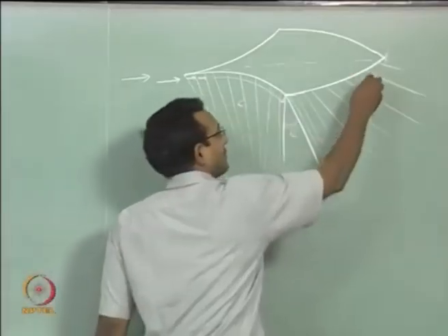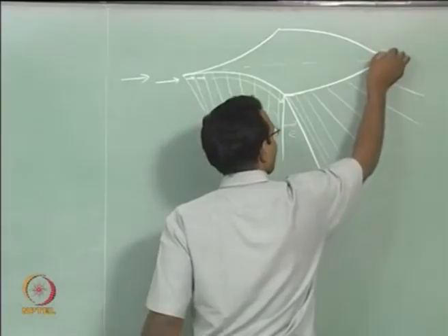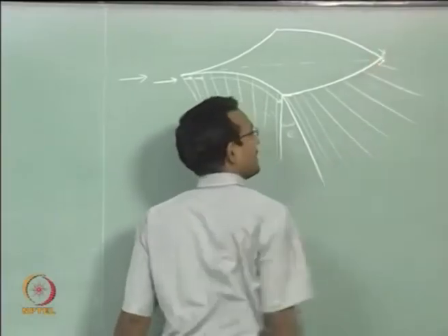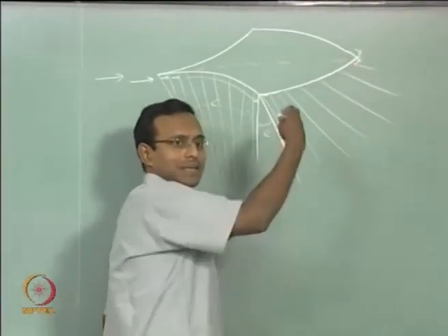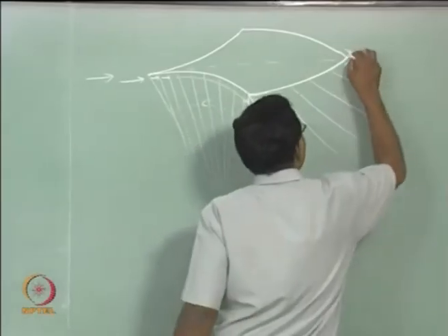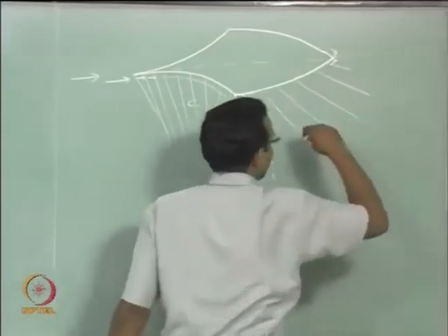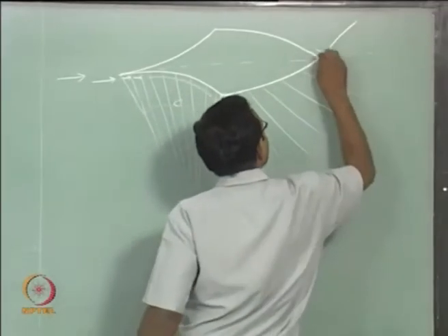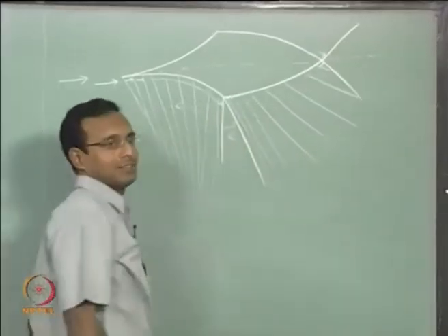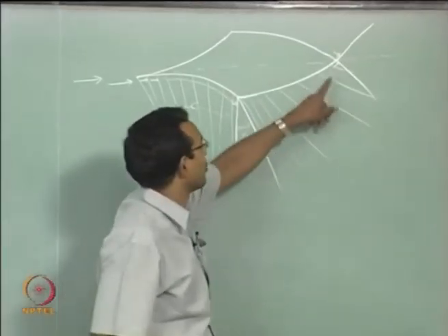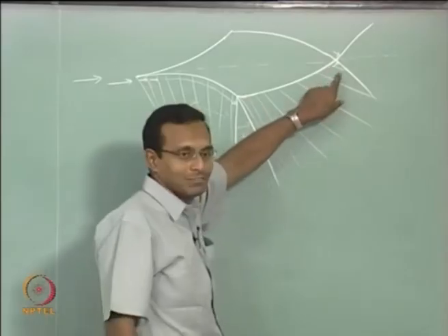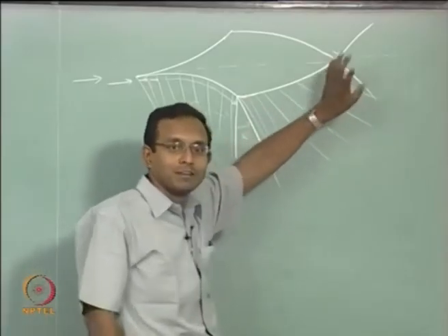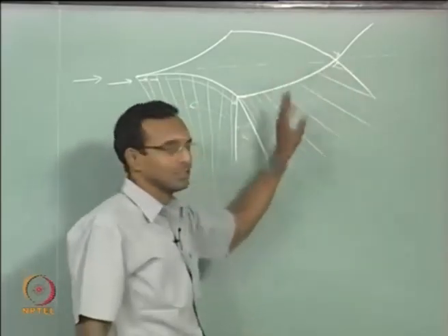After this, since the flow on the top is also very symmetric, the flow will come like this and meet at the corner. This is same as the previous ending, like the wedge problem. It will go parallel to it finally, and you will find that there will be shocks on both sides. We haven't figured out what the shock will do when it interacts with this expansion here. We haven't done that part yet. Okay. It's going to do something like this.